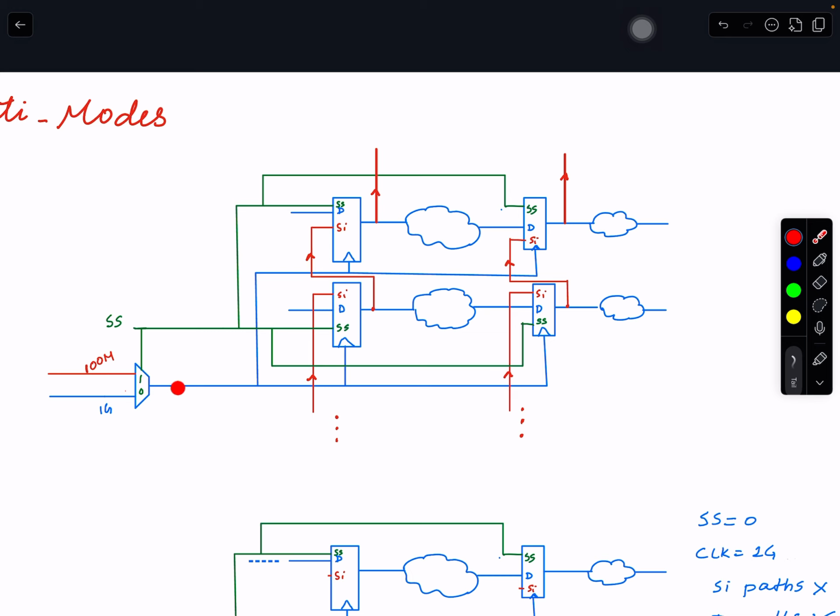At this point, each clock pin is the same, they are connected like this, right? If you get the attribute or property on this pin, and that property is clocks, how many clocks do you see here? All right, yeah, you will see 2, right? This is a multiplexer. There's a combinational timing arc from here to here, and from here to here. So you will see both clocks reach here.